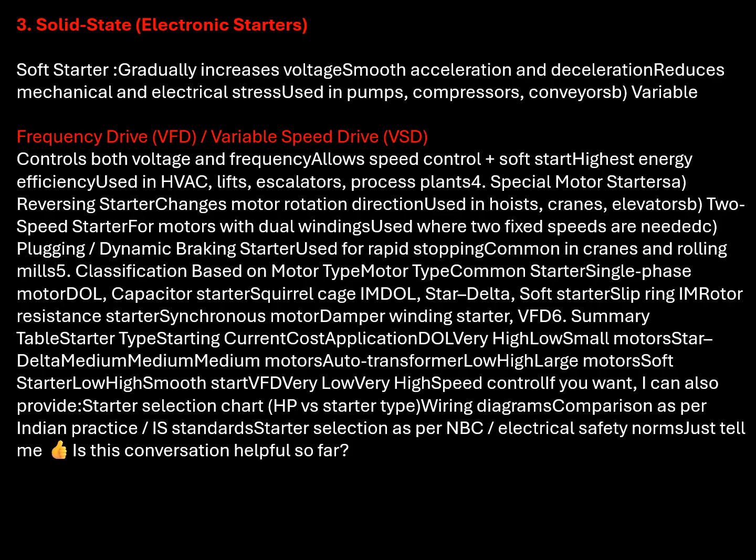Friends, the next category is solid state electronic starters, known as soft starters. Gradually increases voltage, smooth acceleration and deceleration, reduces mechanical and electrical stresses, used in pumps, compressors, conveyors.